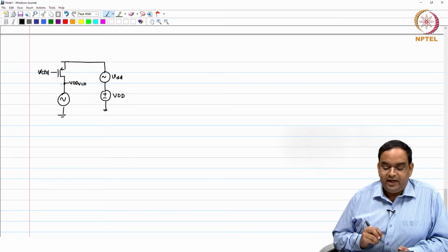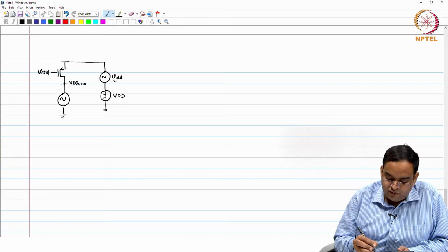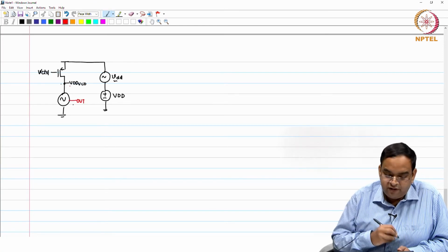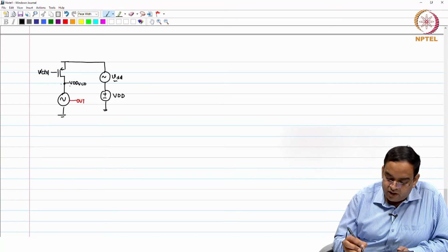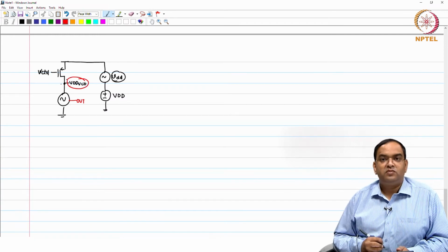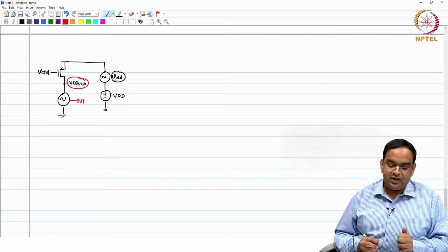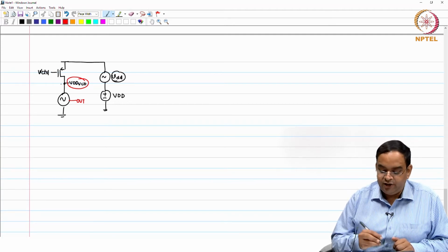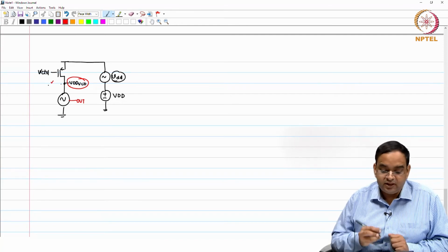In order to find how the supply noise is going to affect my VCO frequency or the phase noise later, I can find out how the supply noise affects my VDD VCO. Because this is noise, which is small in magnitude, I can use a small signal model of this circuit.